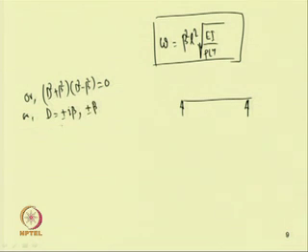So, one can get 4 roots, and from these 4 roots one can find the general solution for psi x. So, the general solution for psi x can be written. When it is plus or minus i beta, the solution will be harmonic, and when it is plus or minus beta, the solution will be hyperbolic. So, one can write the solution.